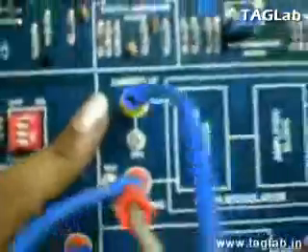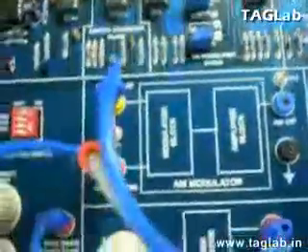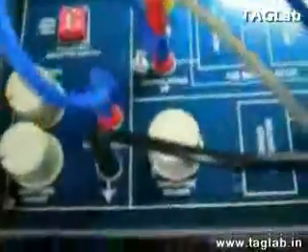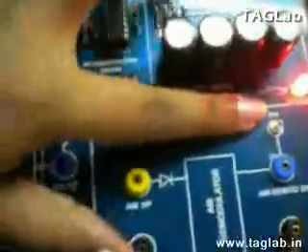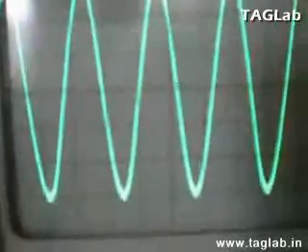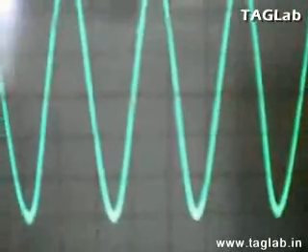Now first let's see the modulating signal. Switch on the kit. The power LED glow indicates the turn on mode of the kit. Now since we have seen the frequency is 2 kHz, on the CRO we could see that it's almost 2.45 blocks into 0.2, which makes it approximately 0.5 milliseconds, which is approximately 2 kHz.